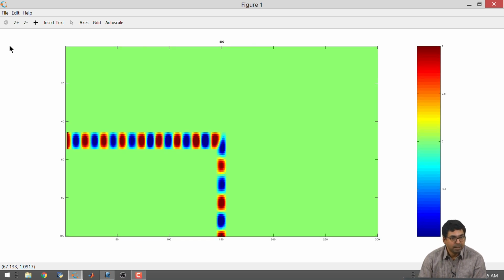Clearly, this waveguide is single mode. So, what happened is, a portion of it started going through the 90-degree bend, and it did not change the mode configuration. But normally one would say that, look, it is not a very conclusive thing. Only thing you can say is, you are getting light from this side and it forms a specific mode pattern, and the light is coming from the other side, it is forming a specific mode pattern. You cannot conclude that it is a single mode, multi-mode and all that, because maybe multiple modes are there and you did not excite them, or the configuration is such that single mode was dominant and then it did not get converted due to several other reasons.